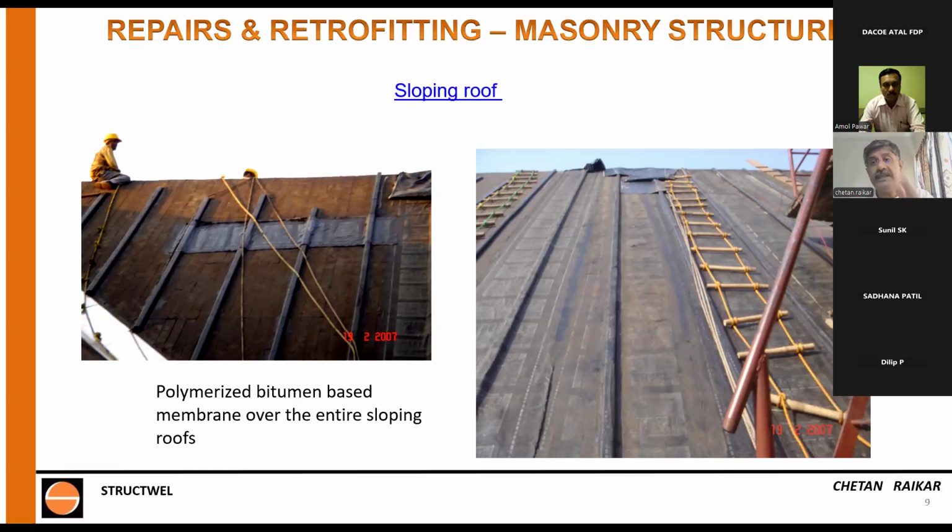So coming back to the point, in VT station, I had to use wood. But if it's not such an important structure, not a grade 1, grade 2 or grade 3 heritage structure, we can always use marine ply. We can use any other, instead of wood, we can use artificial wood also. It doesn't matter really, because we should all try and reduce the use of wood in the construction industry as far as is possible.